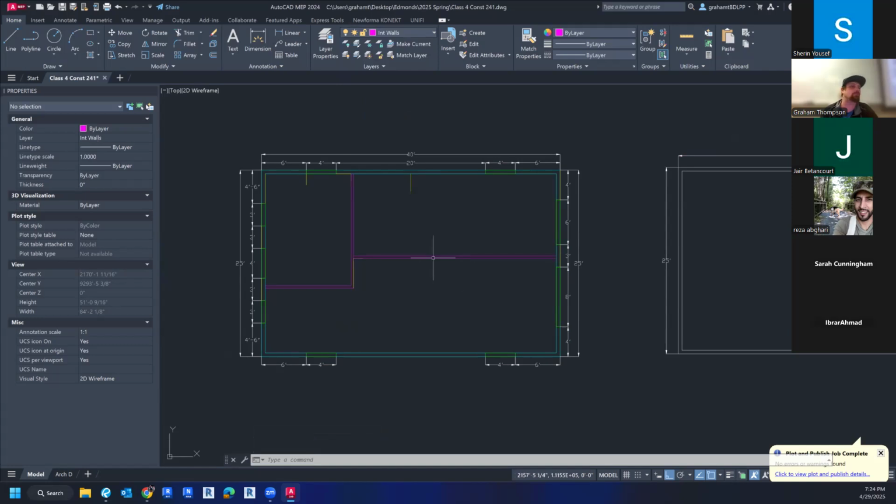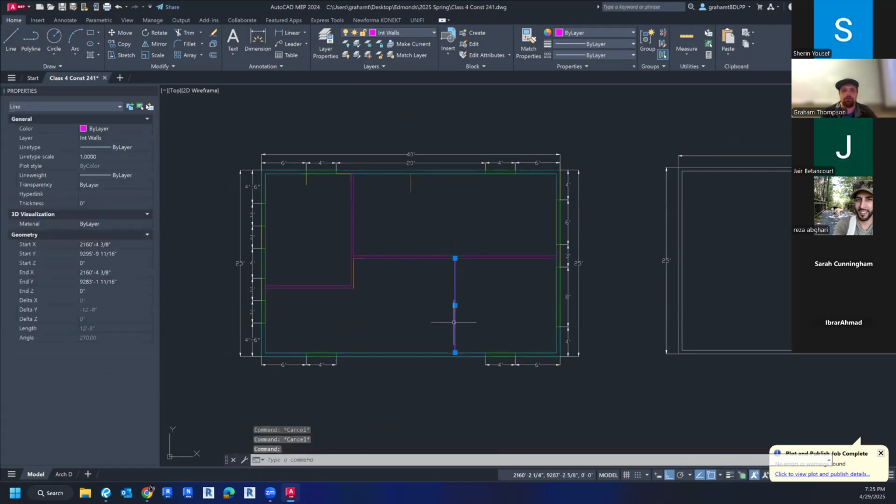We don't need to make a construction line in this case. Okay. If I wanted a certain distance out there, maybe I would need to, but since I know I just want it centered, it knows where center is. So we can draw another, again, line, polyline, doesn't matter. Okay, there's really only a need for a line in this instance. And we're just going to draw that straight down.